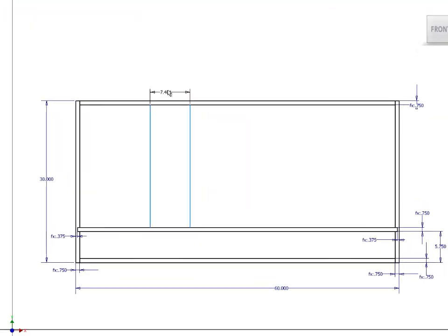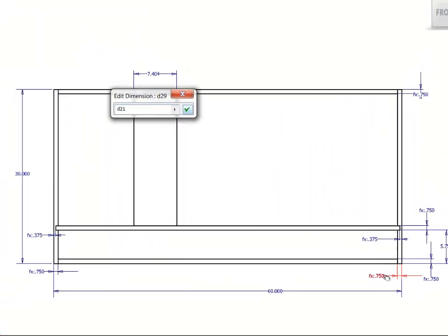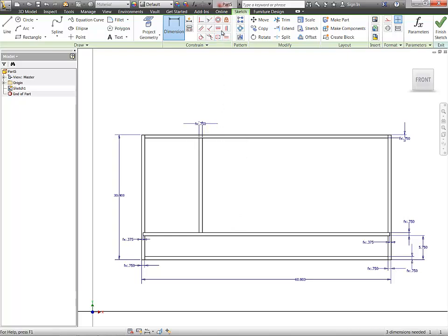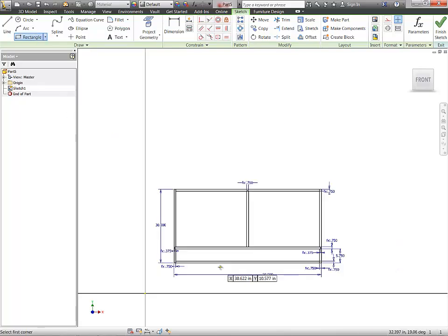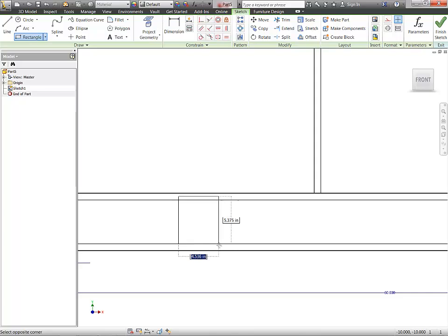Next, let's create a center divider. Center divider will be fixed. We'll say it's equal to thickness, and I'll set it to vertically be placed in the actual cabinet itself. Thusly, change the width of the cabinet, and it stays centered.